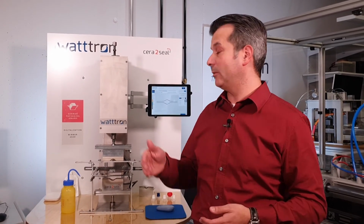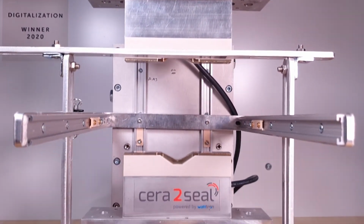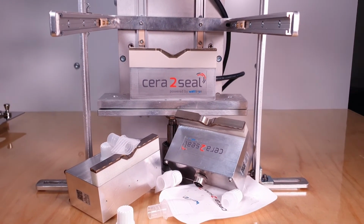If you set too much temperature in the system, then you will seal a tight spout, but you have an optical issue in the rim area. And with our heating system, you're able to control different zones of the tool, and you're able to get absolutely tight and optically perfect results for the spout sealing. This is what we wanted to show you today.